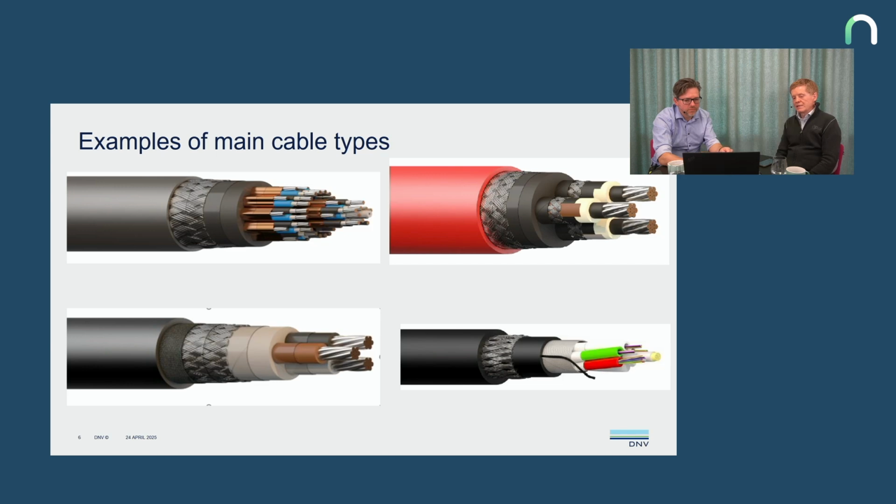And what you can see is that around this tiny cable element there is an extruded inner covering, which makes the cable semi-gas tight, and that is also useful for use in gas dangerous areas. If you did not have this extruded inner covering around the elements, you could have more risk of gas migration along the cable. So that is part of the specification.